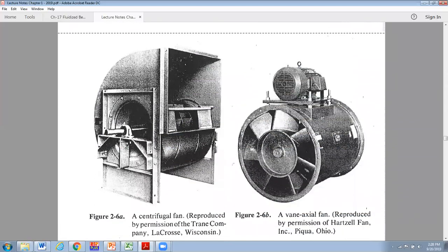We're going to have just some miscellaneous equipment. This would be a large centrifugal fan. So the air coming into this is bolted in right here. If we had inlet guide vanes, they would be set up right there to impart a pre-swirl to the air to adjust capacity on the fan. If we have discharge dampers, they would probably be in the discharge duct up here to just close off against the blast of the fan.